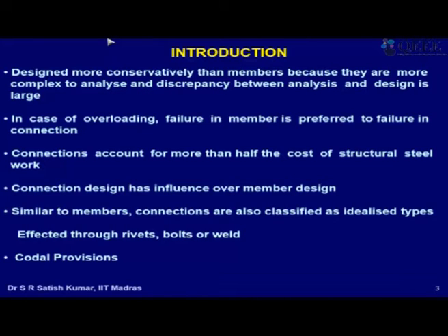Connections are again important from the cost point of view because they account for more than half the cost of the construction, that is the structural frame. And it is very difficult to estimate the cost of connections, because for example you need to drill so many holes for bolts, you need to do so much welding. For welding you may have to prepare the edge by grinding the edge and things like that. All these issues matter, so it is very difficult to estimate.